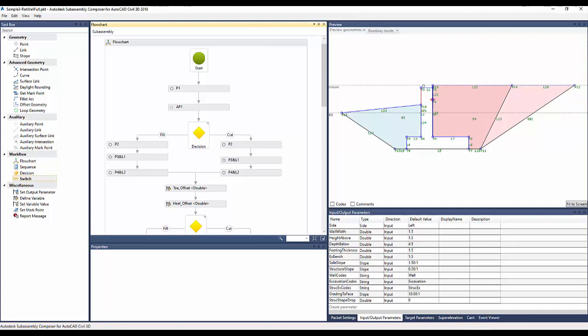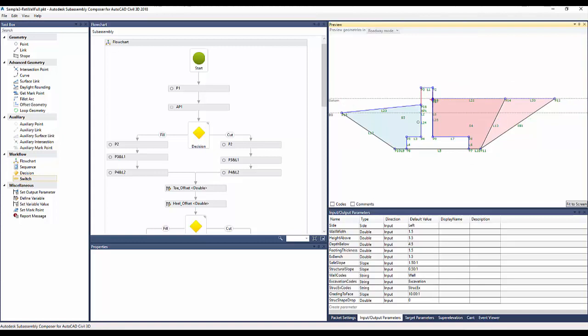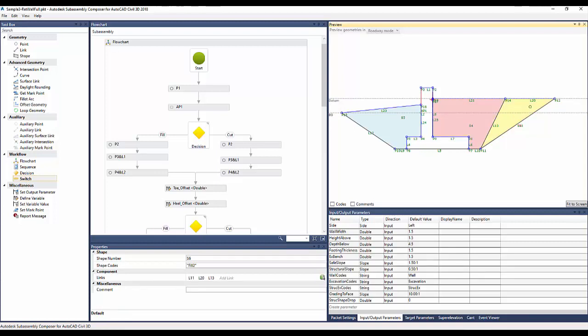So basically, we just push this retaining wall subassembly through very quickly anywhere that we think we may need a wall, and take a quick look at it, and it will drop these shapes in there, which tell us the excavation limits that are required to put the wall in place, as well as 3 different types of quantities that can be pulled out of this, along with a modifiable back grade, some other modifiable slopes, and toe and heel that automatically adjust based on an equation per the height of the wall, and also whether it's a cut or fill. So this is the one that we actually use in the project.